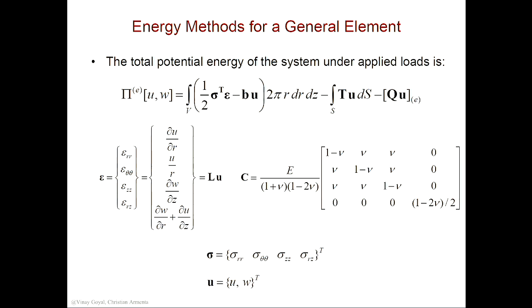You follow? You track? The top one is just one equation. How many equations do you see there? 4? You see 4 equations in the total potential energy? How many vote that there's 4 equations there? So the total potential energy is a single scalar quantity. So pi is a scalar quantity, so there's only one equation here. And we know that because, for example, sigma bold transpose is a 1 by 4, and this is a 4 by 1, so I get a 1 by 1, and so forth. You guys can check the rest. Okay. Any questions on this?